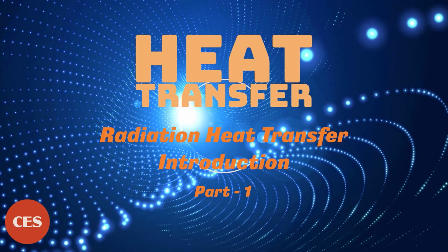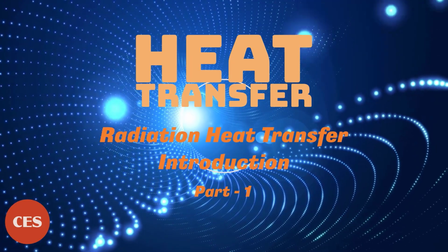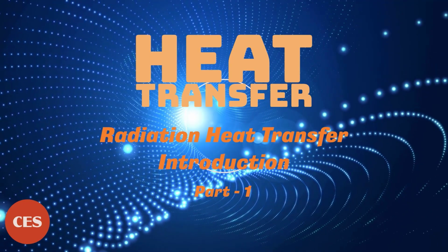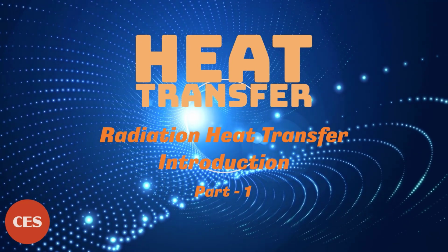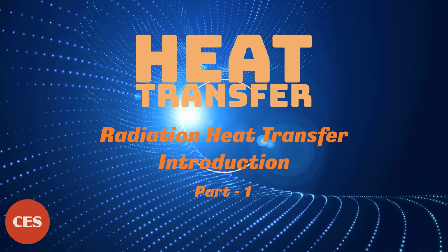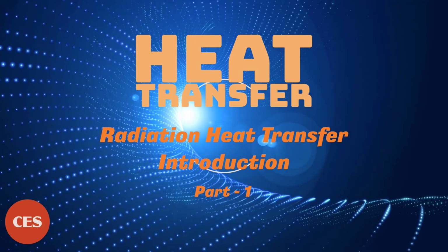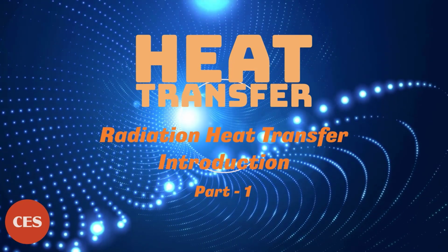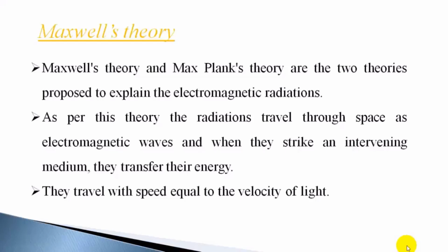Hi viewers, in this class I will discuss another important mode of heat transfer, that is radiation. As all of you are aware, radiation does not require a material medium for the transfer of heat. In fact, perfect vacuum is ideal for radiation heat transfer. Also, all bodies above absolute zero temperature in the universe emit as well as receive radiations. The radiations emitted depend on the temperature.